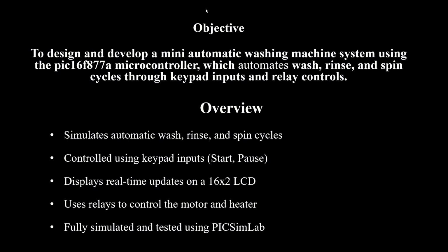The system overview. The project simulates an automatic washing machine system using a PIC16F877A microcontroller. The user interacts with the system through a keypad, selecting the modes and water levels. A door sensor ensures safety by pausing operation if the door is open.